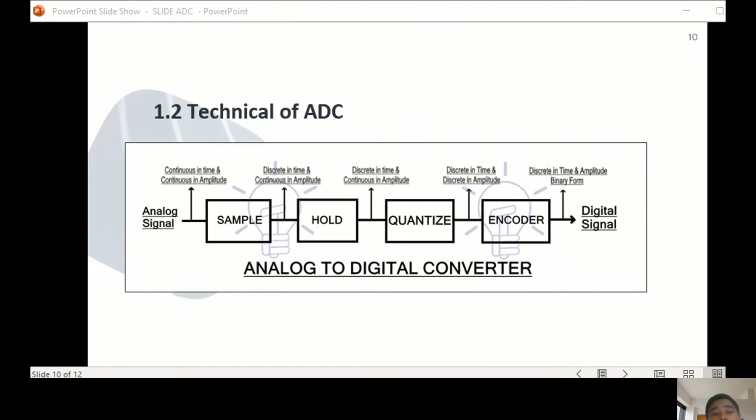The conversion from analog signal to digital conversion can be explained from the figure. The sample block function analyzes the input analog signal at a set interval of time. The samples are taken at a constant amplitude and have a real value although they are discontinuous in time. The hold block is the second block used in ADC. The sample amplitude is only held until the next sample is obtained. Until the following sample, the hold value remains constant.